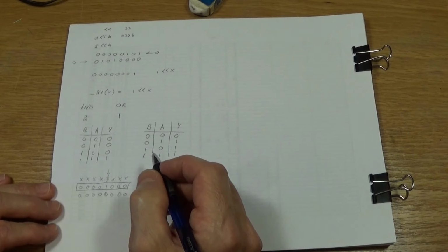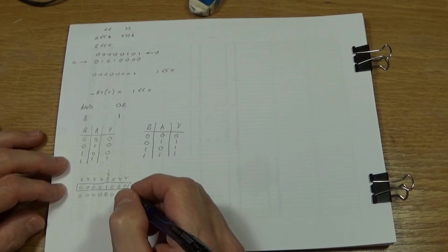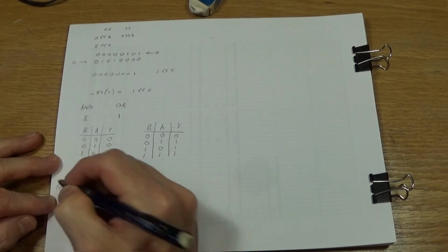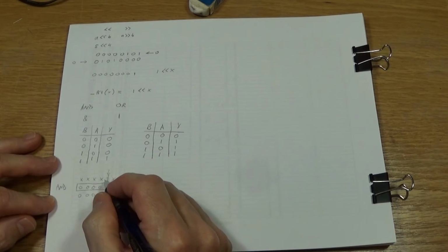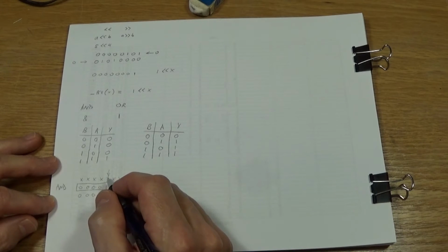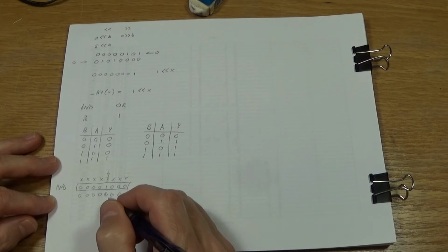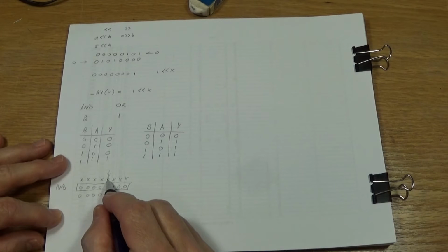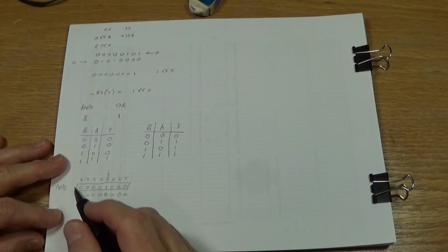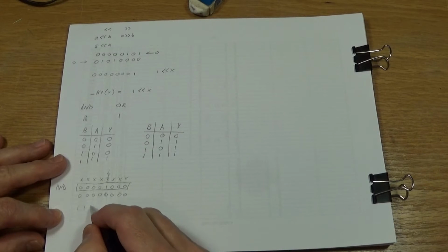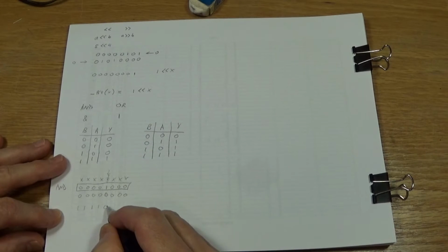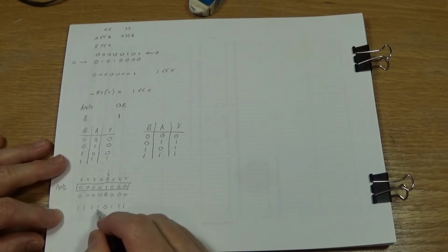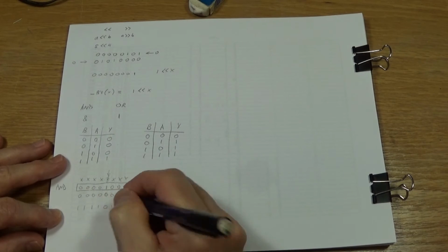If we want to, sticking with the AND function, if we want to make a bit in a register a 0 bit and not affect any of the other bits in that register, we can do it in a similar manner. So again, we have the same register here, and we want to make this bit become a 0. So we'll make our mask all 1s, except for the bit that we want to make a 0. Or bits, it could be more than 1 bit, depending on what you're trying to do.